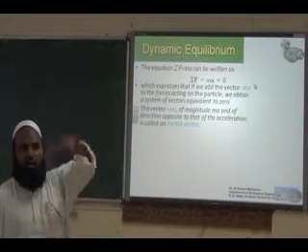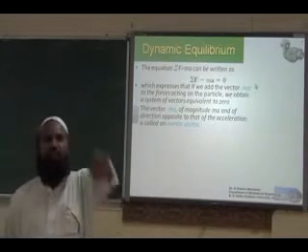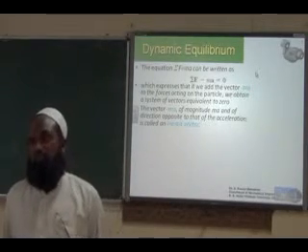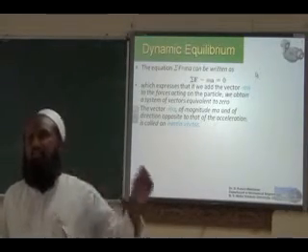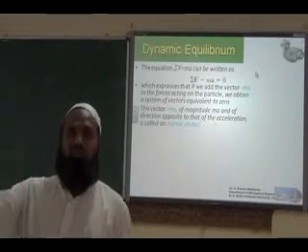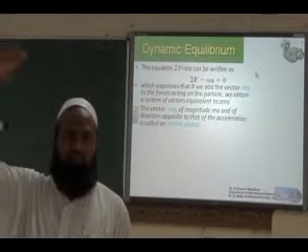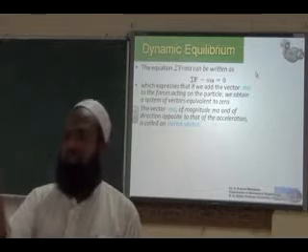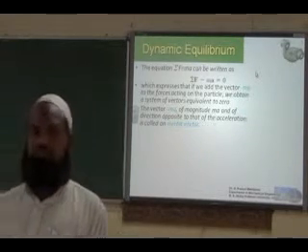We consider all the external forces as well as internal forces acting on the system equal to 0 under dynamic equilibrium. So if you write this equation like this, sigma F minus ma equals 0, this is similar to our equilibrium equation in statics, sigma F equals 0. Here the only difference is we consider the inertial force.